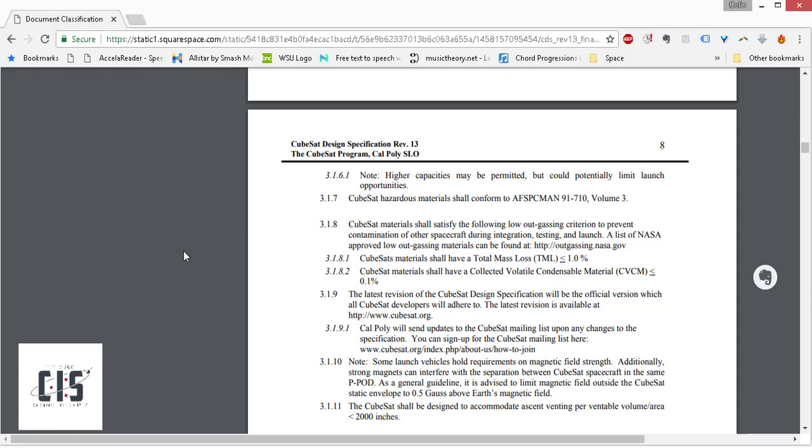So things like metals generally don't outgas. Technically, everything outgasses just a little bit, no matter if it's a metal, if it's solid, no matter how cold it is. But realistically, there's only a few you've got to worry about. Cadmium was especially bad. It's also super toxic, so we don't want to deal with it. And then I think it was zinc, one of those metals, like magnesium. Let's Google it fast. I think you said cesium, and then zinc. Zinc is bad. Magnesium is also bad, apparently.